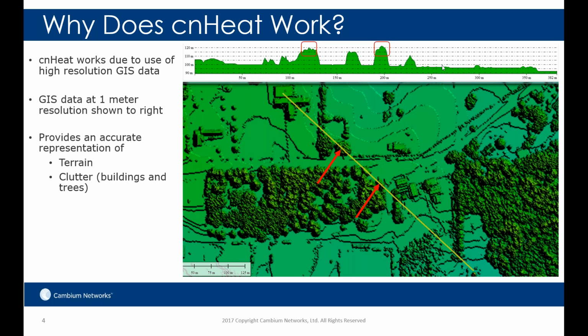And if we look at the path profile, you'll see that here's the back of the church building where you have the service, or the RF. And then here's the front of the church, and it reflects an accurate representation of what the church looks like. Then along the way, you see various higher points, and these are the trees. There are 2 high points that are marked, one here and one here. We can see that the values are 120 meters and 121 meters. These are the points that are going to say whether you get service or not from this access point to the far right.